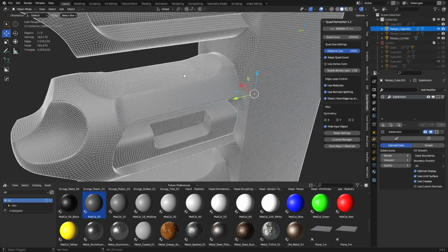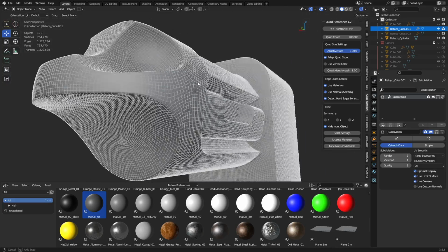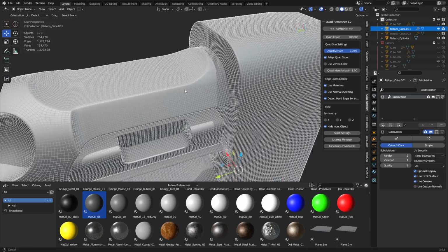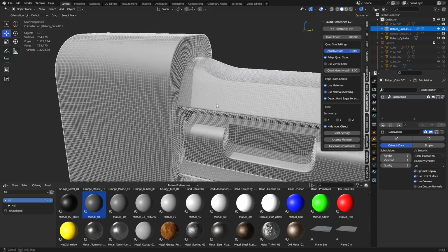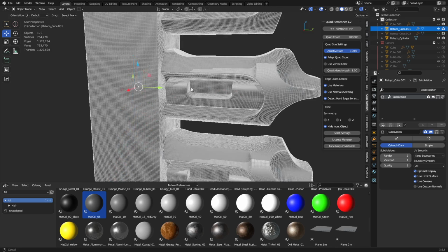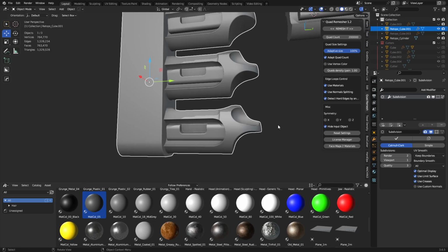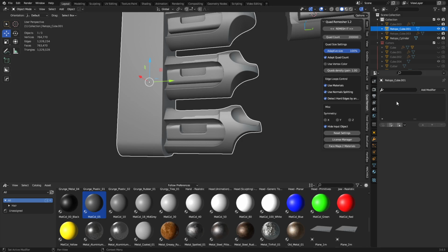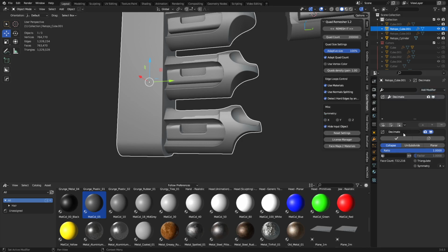All right. So this kind of mesh is really most useful for doing high poly meshes that you want to bake down to a lower poly mesh later on, perhaps. It's not an extremely optimized mesh that would necessarily be something you want to use in a big scene that you're rendering. You'd have to work this down to a lower poly state. And there's different ways you can go about doing that. But you could just apply a level one subdivision and we can go ahead and decimate this. We can do just a regular decimation here and change the value to whatever we see fit.